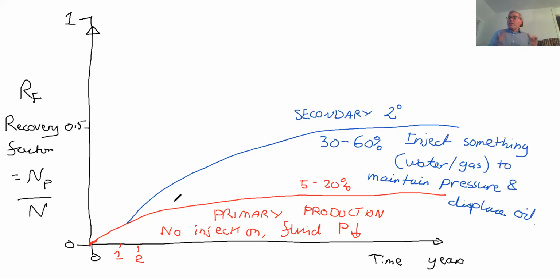So secondary recovery is fluids coming out of the subsurface. If you inject the same reservoir volume of something else, you're going to maintain pressure. That's just simple material balance, again, a subject that's coming later. So you inject something, and that something is normally water, normally seawater or water from an aquifer, something that's cheap. So what that does is keep the pressure high.